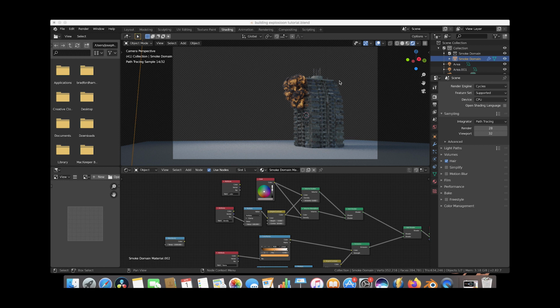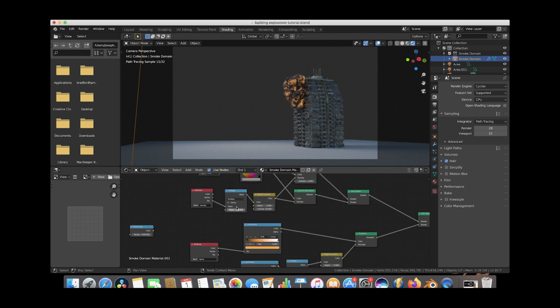Alright, so it took a little while to get the smoke materials right, but I found some settings that work pretty good for it. Since we're going to add some glow and glare in the compositing process, I've put the density value at 108 with the contrast of 20. Normally I don't put the contrast this high, but for whatever reason in this specific bake, the smoke was cutting up the flames very nicely for this larger scale smoke look, and it worked pretty well. So yeah, that's what I tried there.